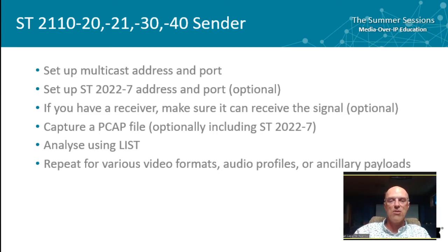And LIST is also a free software that got developed basically for our industry to do these very tests by the EBU. LIST will open up the file and analyze all the packets in there and look at the timing of all the packets and compare them to the spec and make sure it conforms to the spec, that the timing is good, that there's no error, no missing packets, that all the timestamps are correct and all of that. And these tests are done and repeated for various video formats you want to test.